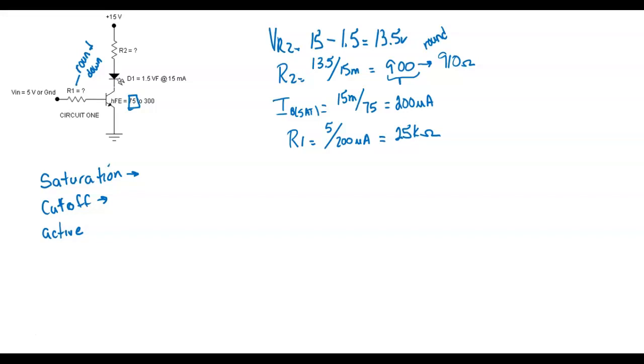How can we tell it's saturated? Not the amperage, volts, but what voltage? If it's saturated, what voltage should a transistor drop? This is a very important voltage measurement.